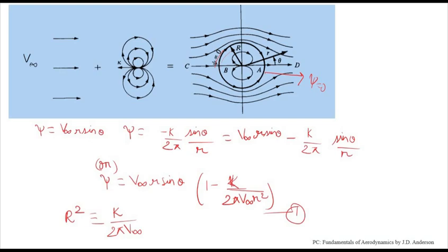So what happens when I say the pressure distribution is symmetrical about both the axes? That is over the top of the cylinder and over the bottom of the cylinder, the pressure is being balanced. That is, the pressure at the top of the cylinder is being balanced by the pressure distribution over the bottom of the cylinder. So when there is a balance of pressure, there is no lift created. This generation of lift part we will also be seeing in future when we consider the airfoils.